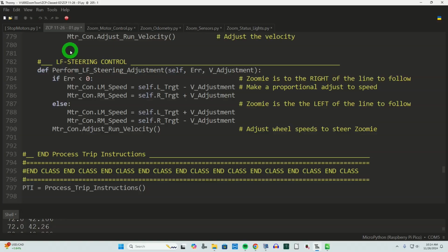Cruising is when we're driving along any road that's actually guided by our guideline. It'll have the inch markers on it, and it'll have the 0 set magnet and the preset position magnet. So there's a lot of stuff going on during that movement, also including a variety of QR codes placed along the roadway. So this one has a lot more sensing going on all the time, and the code base is a little bit longer on it, but it's still not too bad. That's the whole thing, for it to drive along and check all those sensors, etc.